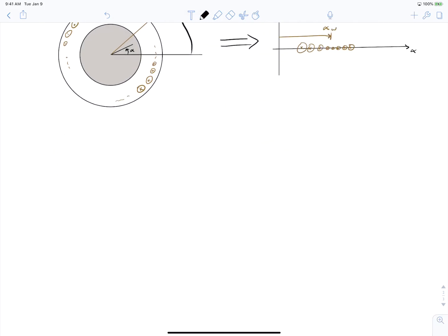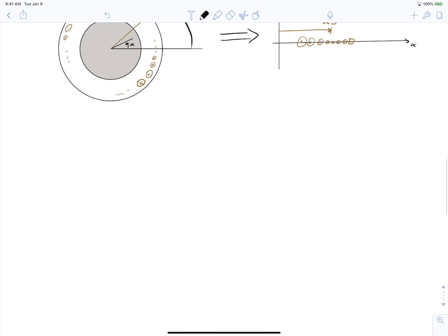And we can summarize what we've observed and done here by saying that the full story is that we start with a motor with windings that are in slots, with coils that are in slots. And from that we notice that we can express the circumferential current density of our winding as a harmonic series.